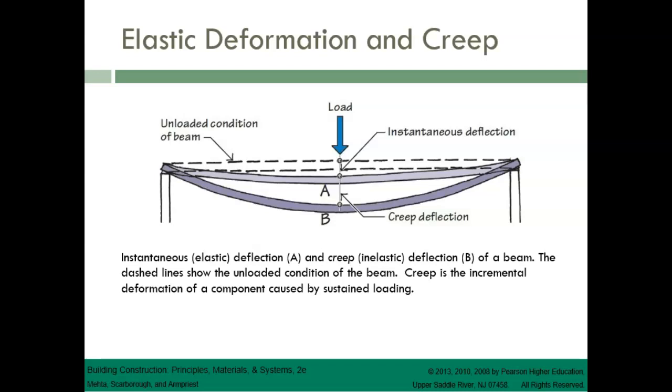Let the instantaneous deflected shape of the beam be represented by profile A. If this load is a permanent load, the beam's deflection may progressively increase and eventually assume the deflected profile B. This time-dependent additional deflection of the beam is known as creep deflection, and the associated phenomenon is called creep. Thus, creep is the incremental deformation of a component caused by sustained loading.